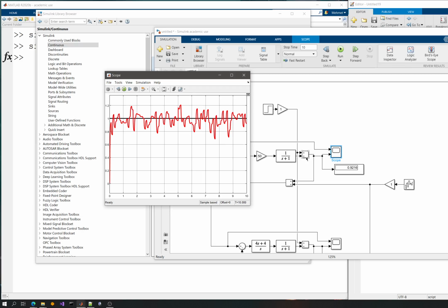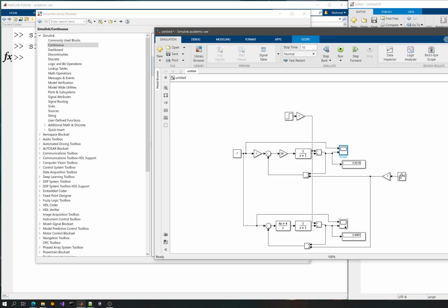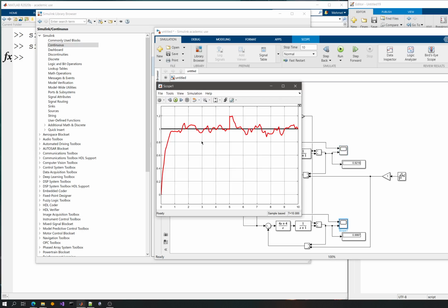You will have this measurement noise, and it is inevitable here. But my PI controller still tries to track the output, and you will see that it will try forever because there is a dynamic component in the controller, namely the integrator, which causes this reaction and which can be used as memory.